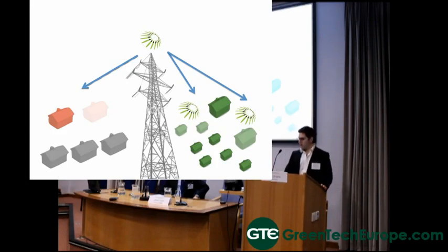What demand response does is install software and hardware at the grid, and at consuming sites. We turn down their consumption temporarily by a very small amount. By doing so across enough sites, we aggregate the portfolio, and National Grid doesn't have to switch on a peaking power station. So economically, rather than National Grid making a payment to these power stations, they're paying the consumers to be more green.